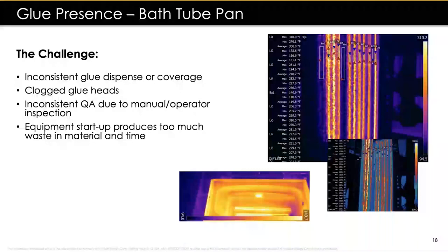So basically, once the product was sprayed, the operator was to visually inspect this product before it was married to its shell, and this product in fact was clear onto a white frame, the subshell underneath the pan of the bathtub. So it was kind of difficult. While you may be able to see whether or not glue was applied, if you can see in the image here, I don't know if you can see my mouse, there could be a line that was missing on the edges right here. So you see these two edges where we're not getting enough coverage from the adhesive.